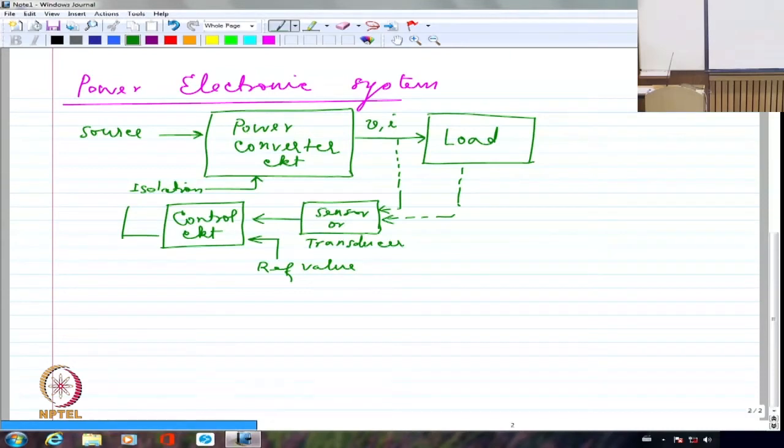So the currents that are flowing are of the order of hundreds of amperes. Whereas electronic portion will have only milliamperes or 1 or 2 amperes. So if something goes wrong in the power portion, I don't want that current to circulate through the electronics portion. If it circulates, it will end up burning the entire electronics portion. So the grounds invariably have to be isolated. So the isolation circuit essentially functions as a protection against burning the electronic portion of the circuit. If there is a problem in the power portion, that will not affect the electronic portion.